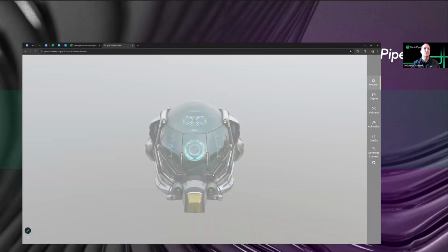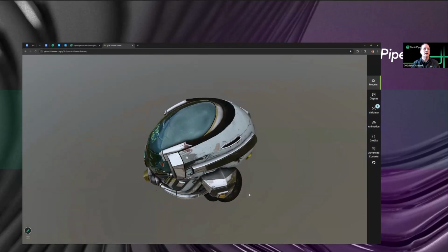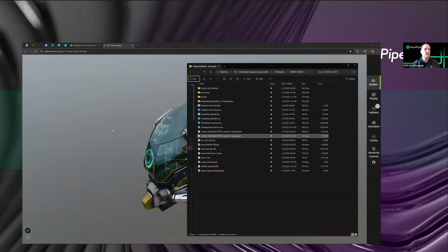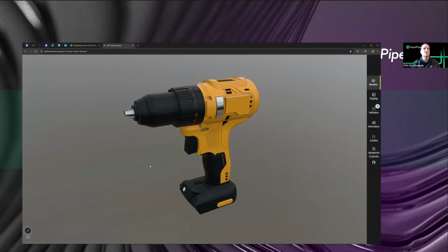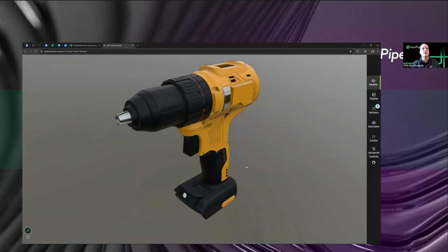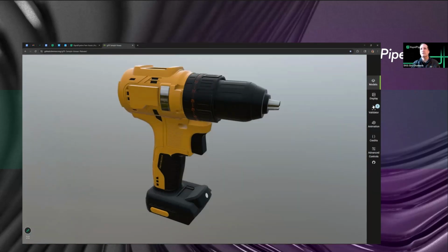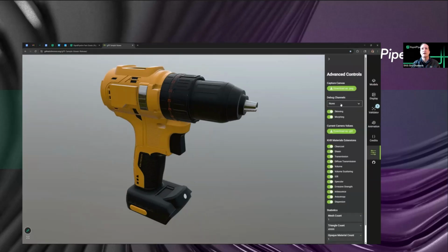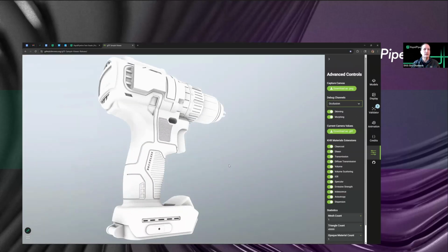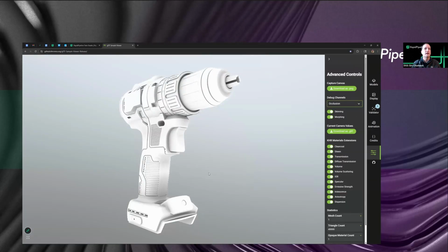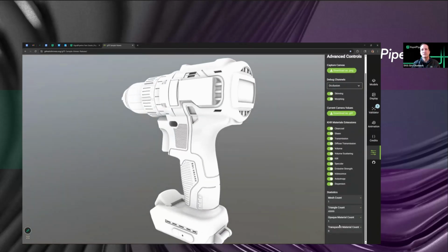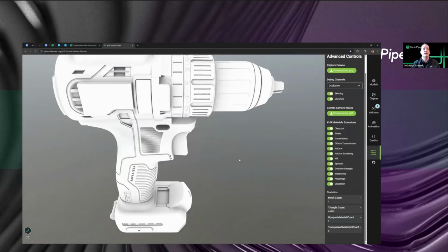This is the glTF sample viewer. It's a default one for looking at GLB files. Let's find our folder and drag and drop this in, and we can look at the model. So there it is. Now it's a real-time exported 3D file with our material assignments that we made and with an ambient occlusion bake. So we can look through the advanced views here and the debug channels. You can look at the actual occlusion that's baked. And you can see it's nice. It's a very noise-free ambient occlusion texture. There's one mesh here, less than 50K triangles, one material, really very efficient.